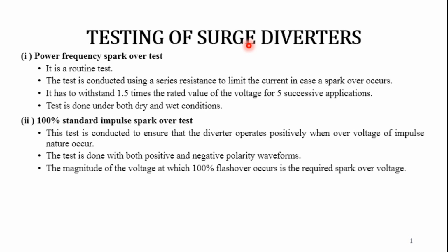So hence, testing in a precise way, and standardization in the laboratory with standard test procedures, are of great importance in modern power system engineering. The surge arrester has to be a non-conductor at power frequency voltages. It should behave as a short circuit for transient overvoltages of impulse characteristics, discharge the heavy current and recover its insulation without allowing the follow-up of the power frequency current. There are different current ratings of the surge diverters that you can see.